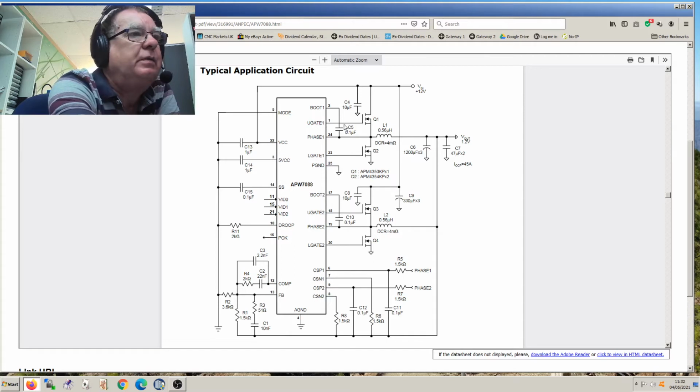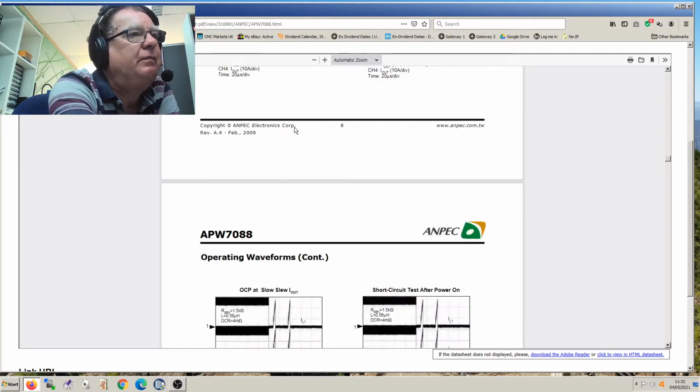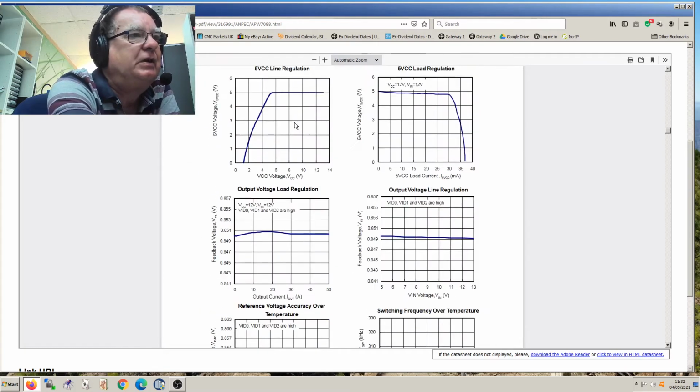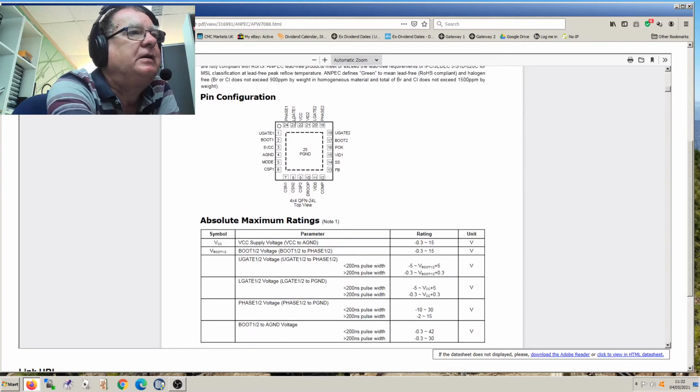In our case, we appear to have a low value resistor in this circuit, or maybe just a 0 ohm used as a link. So one of them goes to pin 1 and one of them goes to pin 18, and we know that goes to the gate. In our case, we can see from the circuit board, the resistor goes to the gate, so the other side of the resistor must go to there. So here it is. There's a dot on the chip, and pin 1 is by it, and then we go anti-clockwise, and pin 18 is up here.